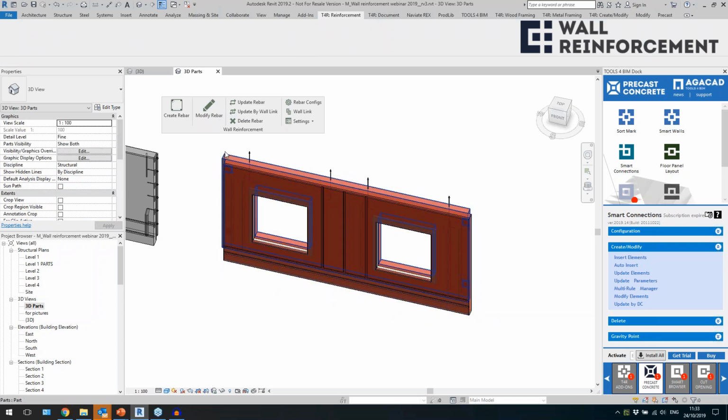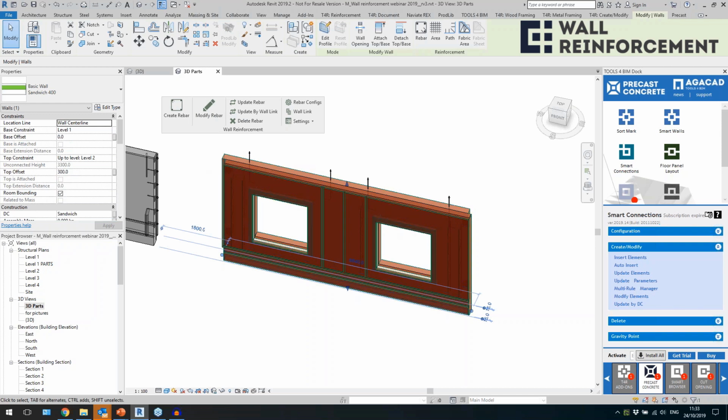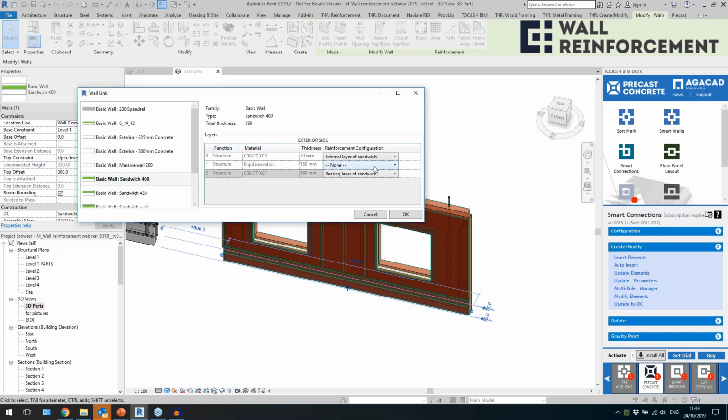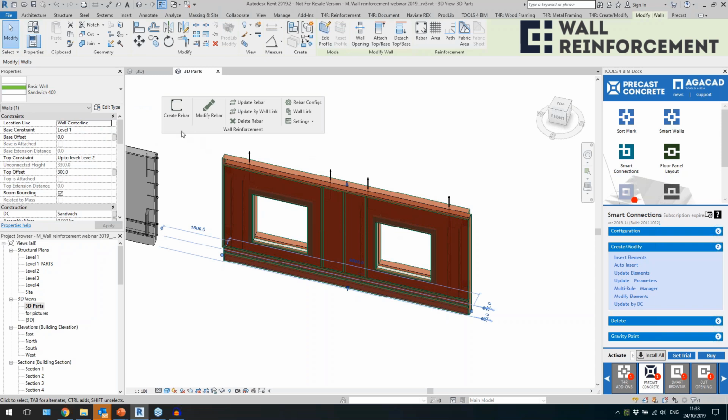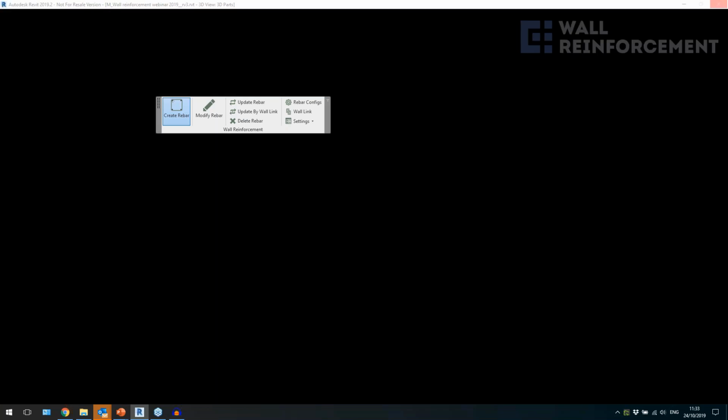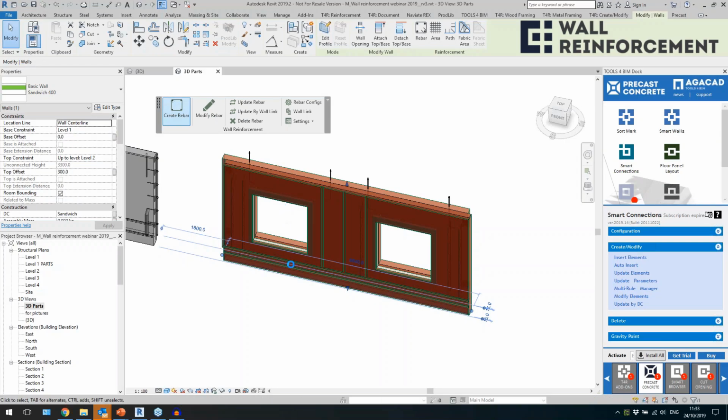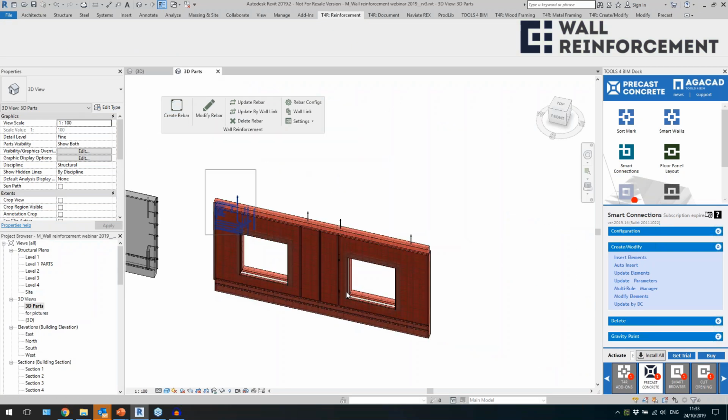Is this that now? Okay, so I see both of them. That's okay. And then I will select this wall. Let's take a look, yeah, we have configurations assigned, create reinforcement, and let's see results. Now it's just calculating the geometry of both layers of reinforcement, and I have quite plenty of reinforcement selected here. So let's wait. All right, should be coming. All right, good. So we have these walls and reinforcement, right?